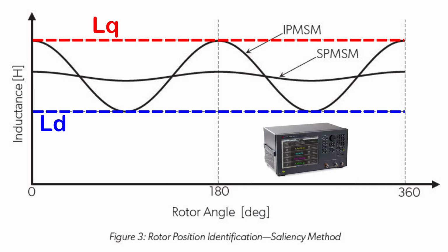Firstly, if you have an LCR meter, and assuming the cogging torque isn't too strong in the motor, you can measure the inductance between two phases at different rotor positions. The minimum inductance you measure divided by 2, since you're measuring across two phases, is LD, and the maximum inductance divided by 2 is LQ.